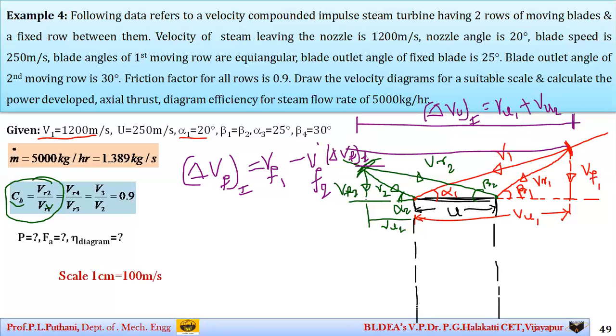And somewhere here, I will draw my tangential speed u. Okay. So a little bit top, I will take it this one. Somewhere here, I will draw u. Okay. So this is the same tangential speed. Once more, I am repeating, any number of blades are mounted on that particular shaft. The shaft speed remains the same, and the tangential speed. That is the reason that the u also for the second stage remains the same.